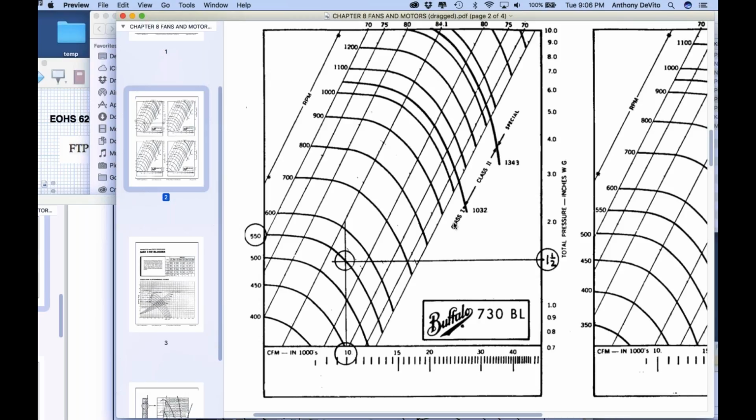And that is because a small change in the amount of air that you're moving, a small change in the static pressure, right? See how flat it is there? A small change in the static pressure can make a big change in the quantity of air that you're moving. Right down here, the slope is bigger. The slope flattens out like that, one can affect the other disproportionately.